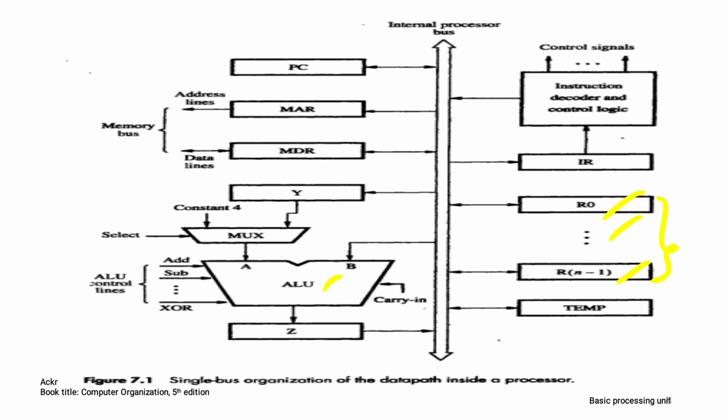This is the arithmetic logic unit. Two operands are given to it. Then, depending on the signal the control logic sends here, the ALU performs arithmetic or logical operations on these two operands. And the result generated will be saved in the Z register, and over the internal bus it will be sent to the general purpose registers for storage.